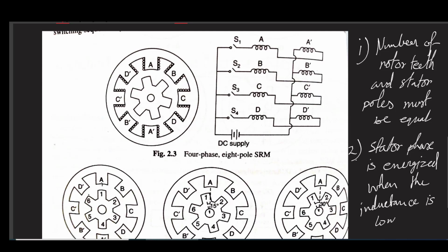Now, how can you know that? For that you need a very specific piece of information regarding your rotor position, collected by the rotational encoder or whatever you have mounted on your machine shaft. That must provide you very particular information about your rotor position. Based on that, you can change the sequence. Otherwise, if you do not have that information, the switching won't give you the desirable effect.